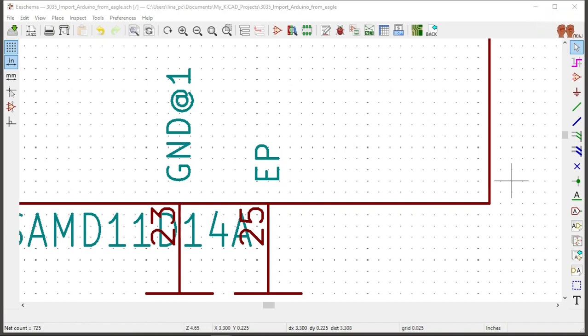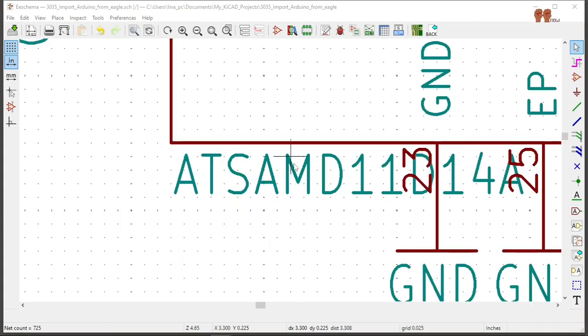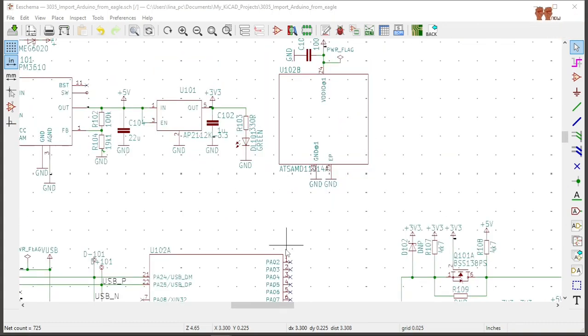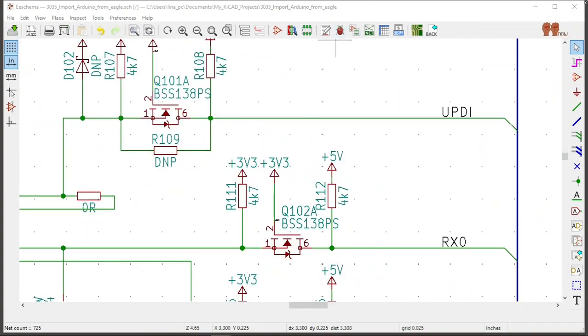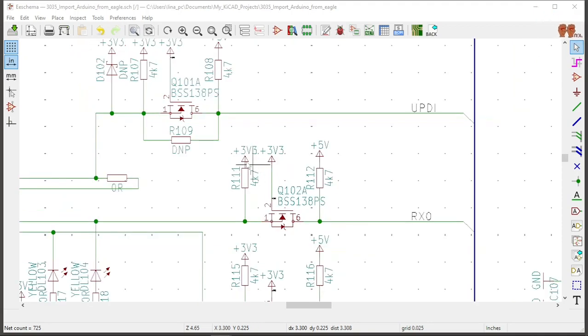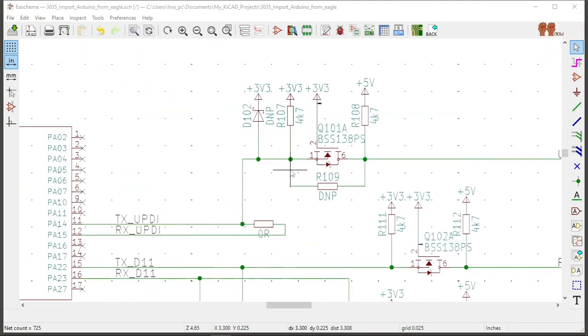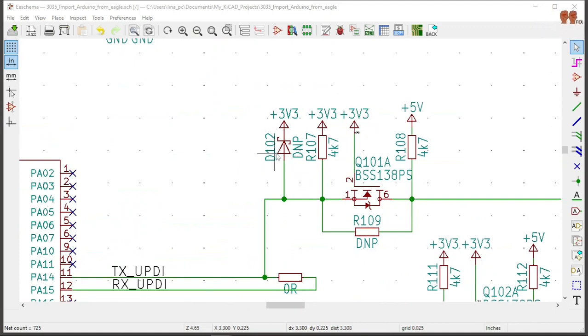Because usually when you do footprints, it has numbers on it, and based on the numbers attached to the pins. But when you start mixing numbers with letters, it will have a conflict, and that's what I found out with the dial.